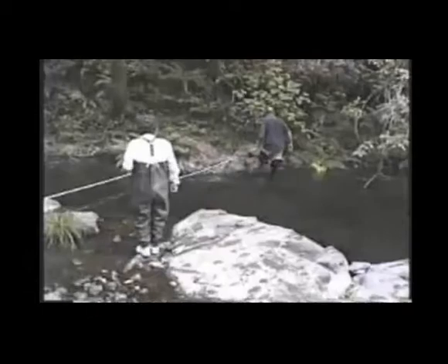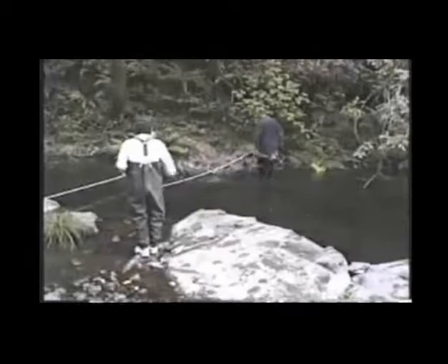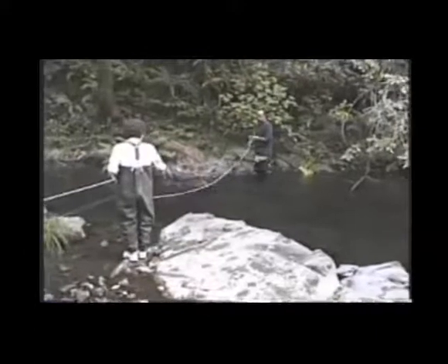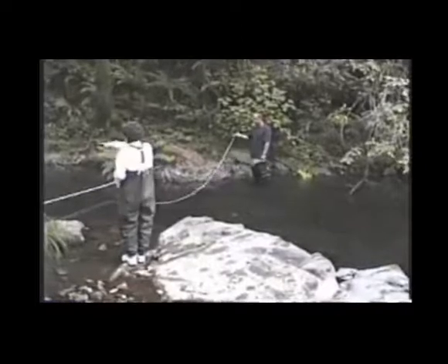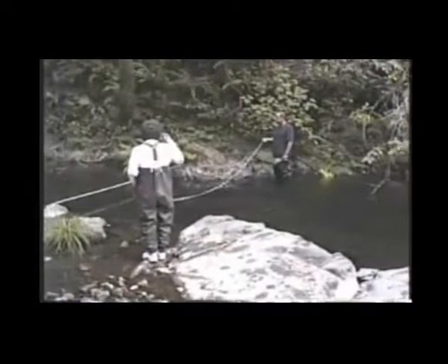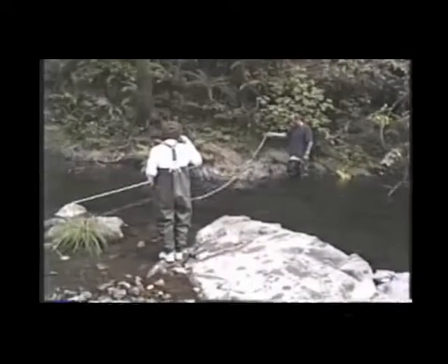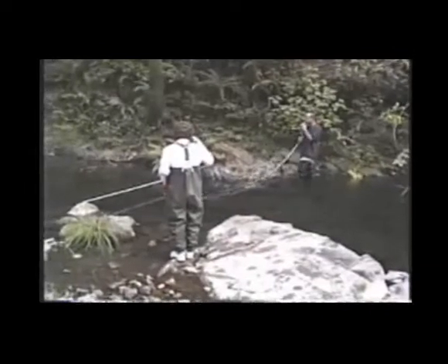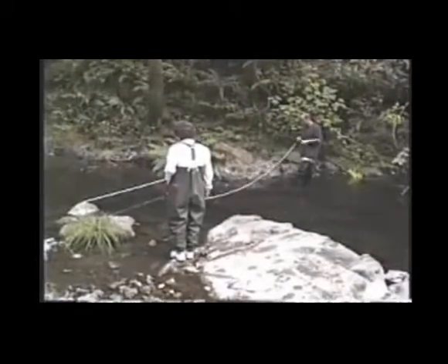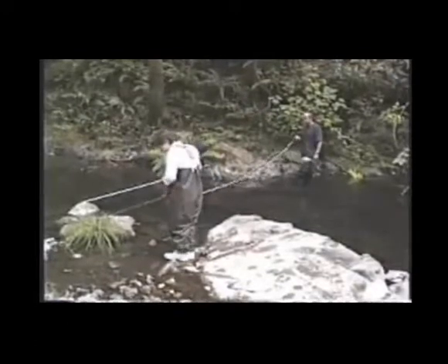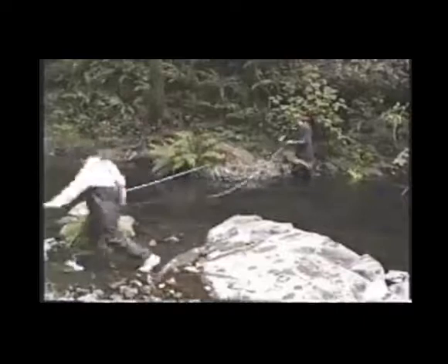This clip is a demonstration of the measurement of a flow across a wadable stream using a bucket wheel velocity meter and a handheld readout device. Here you see the team reconning the stream. The idea here is to find a suitable place to measure the flow. The bottom should be fairly even. The sides of the stream should be even as well.